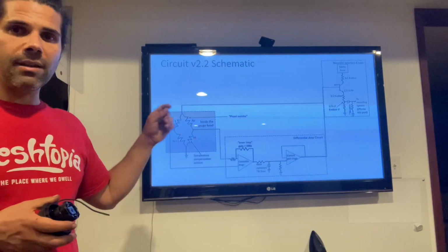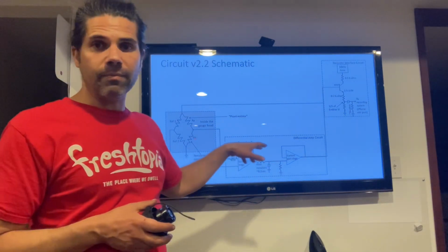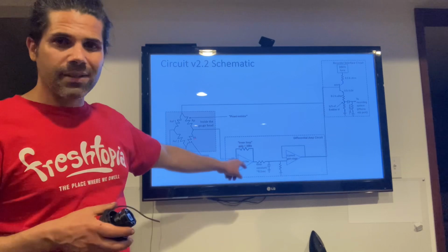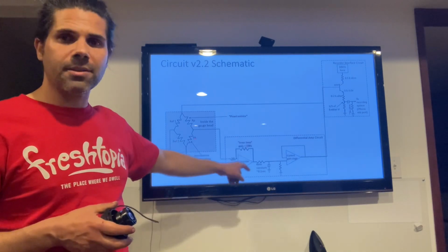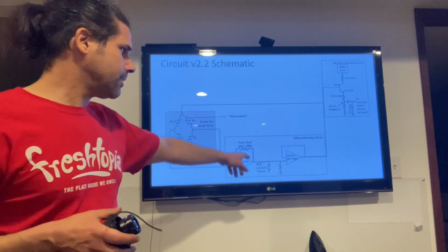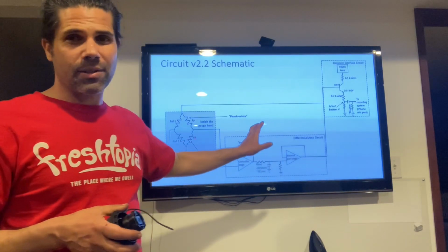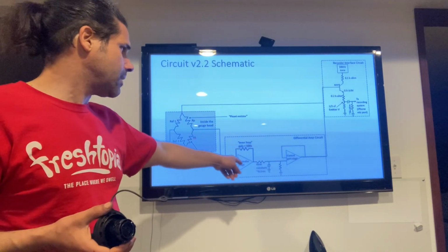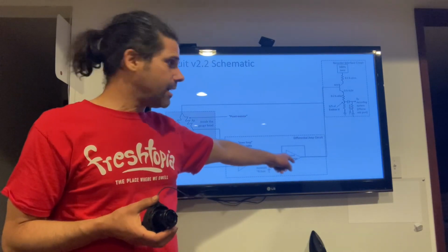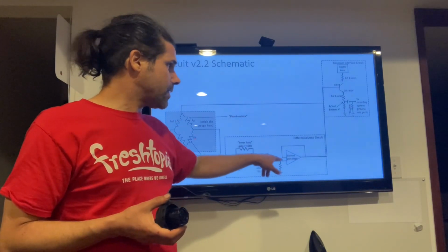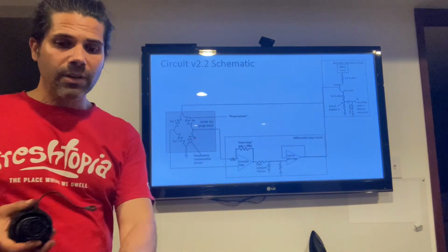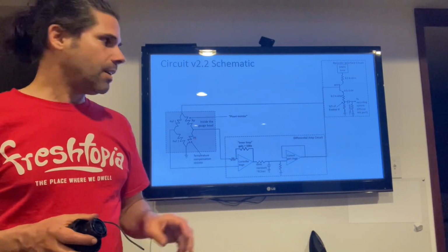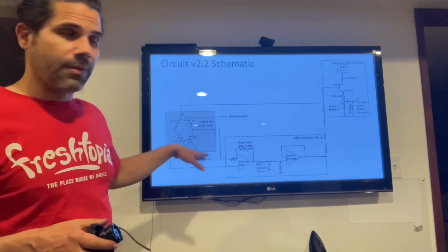So the circuit I built is basically a two-stage system. The first one does the comparison. I've got some time constant on it just because I didn't want it to move too fast. I'm using this from another application that needed that, but this one you could take off the time constant and it would be fine. And then I have a current gain stage. It's basically both in the same package. My Pirani has a little bit of a low resistance, so I needed a fair amount of power capability for it to drive to get the full range of the gauge.